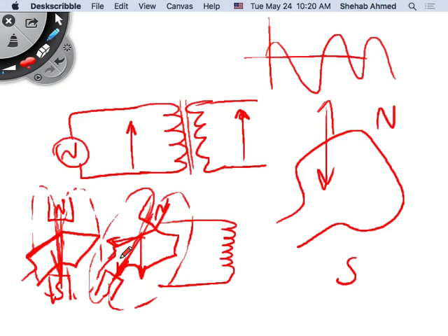the component that is cutting the turn perpendicular to its cross-section area is going to change in value. Originally it was perpendicular, so all the magnetic field is going through this turn perpendicularly. If I turn the magnets to one side, this causes a component to be in this direction and a component to be in another direction. This other component is not going to link my turn at all, so it's a different value of magnetic field. And you keep doing this, meaning you have a time-varying magnetic field that is linking a turn. What did Lenz's law say about this?